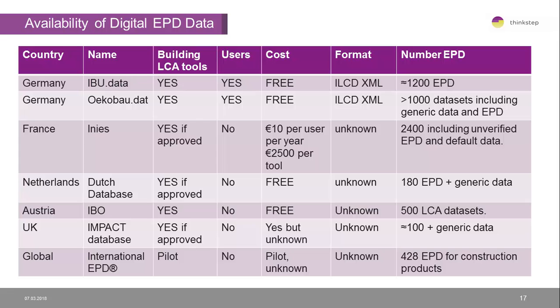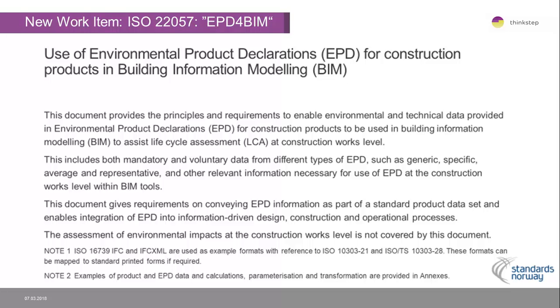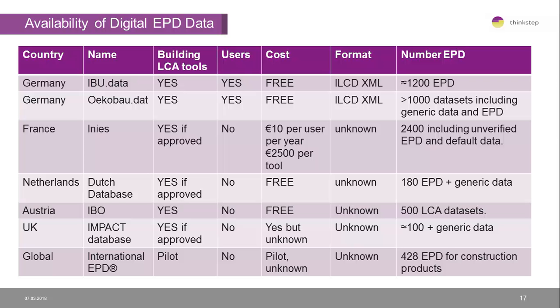In the Netherlands, again, it's regulation to do building LCAs with their Building Act. They have a Dutch national database. If you get your tool approved, then the database goes into your tool. In Austria, they have a free database. In the UK, there's the BRE database, which tools can apply to use. We don't know how much that costs. We believe it costs. And the International EPD program in Sweden is piloting the provision of digital information. So all this data is out there and available to go into tools already as we speak.